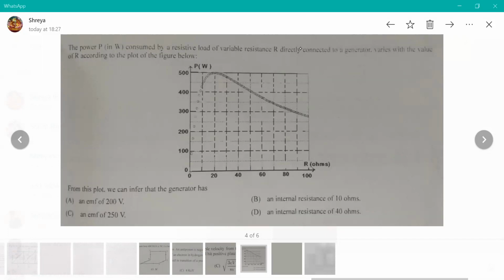So basically this corresponds to this kind of a circuit diagram, that imagine you have connected a load resistor across a generator, which you can treat like a DC source, which has some EMF and some internal resistance. Okay. So the power consumed by the load resistor is I square R. So that is E square R upon (R plus r) whole square. Okay. So as you know, this is maximum when capital R is equal to small r. Maximum power theorem. Remember that, Shreya?